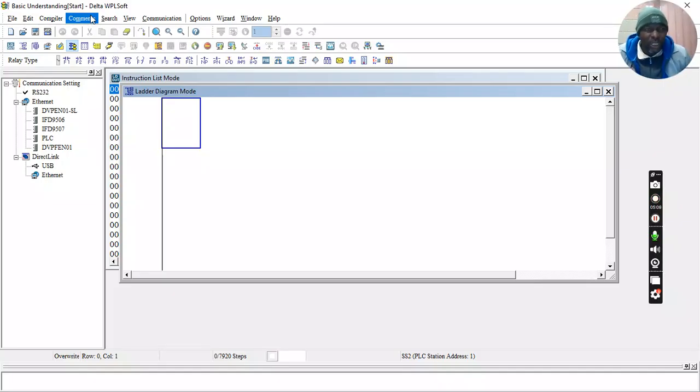hardware spaces, we would actually use switches. Here we use a switch has a contact, because where you wire onto a switch, where you wire your power in and your power out on a switch, those are contacts. All right. So we use the language of contacts here with PLCs. So I'm going to put a contact where I'm going to wire my start switch. All right. So I'm going to use that contact.